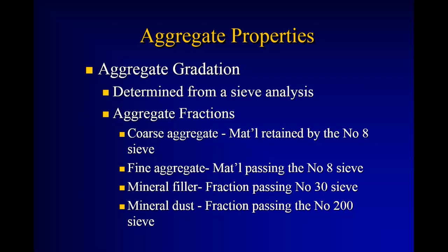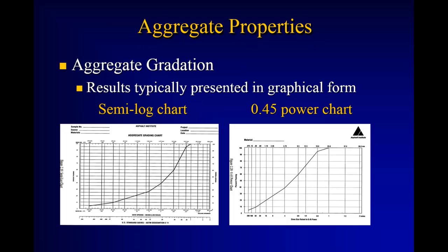Number one, it's typically more solid, more stable material. It's angular in a lot of our sand and gravel pits in North Dakota, but you can get too much of it too, and then it can make the mix unstable or the aggregate blend unstable. But the 200 particularly is called mineral dust. And if you think of the material that would pass through a number 200 sieve, it's still an aggregate material. We call it mineral dust, but it almost flows like water, and a relatively small amount can have big impacts on an asphalt mix.